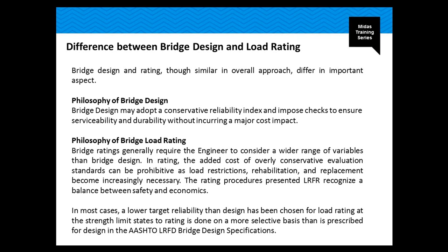The rating procedures presented in the LRFR, which is the code that we're going to go over today, recognize a balance between safety and economics. In most cases, a lower target reliability than design has been chosen for load rating. The strength limit state for rating is done on a more selective basis than that prescribed for the AASHTO LRFD bridge design specifications.